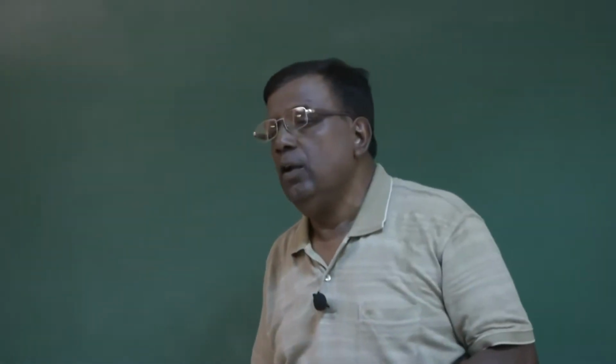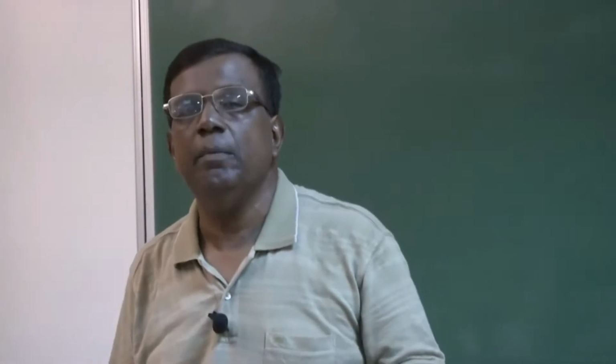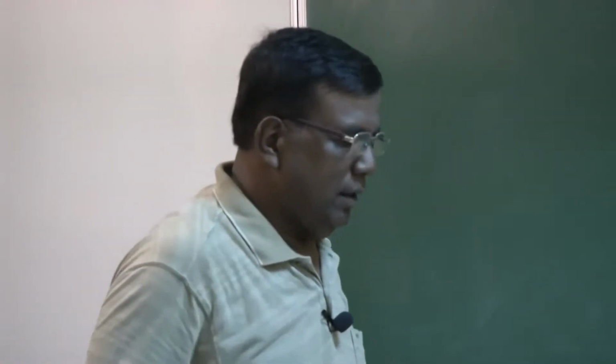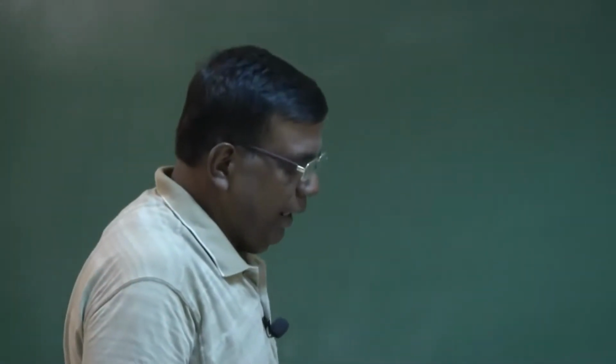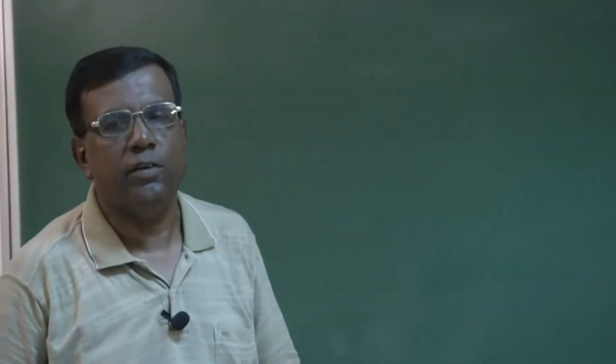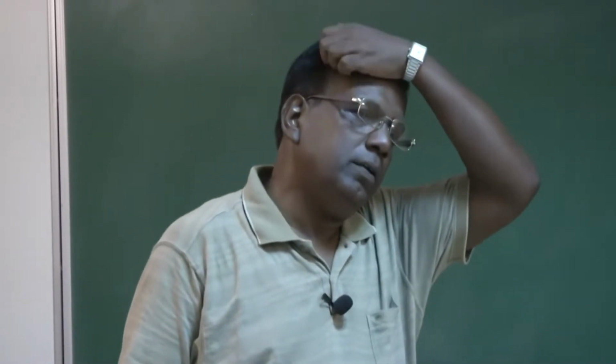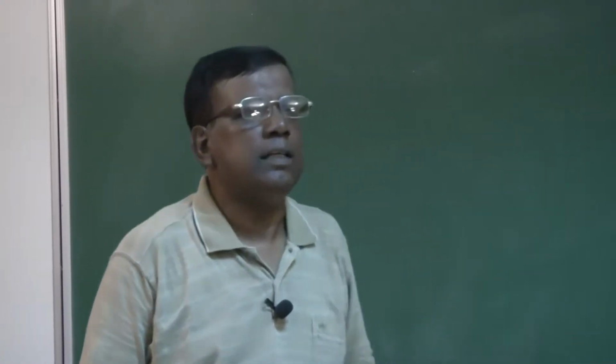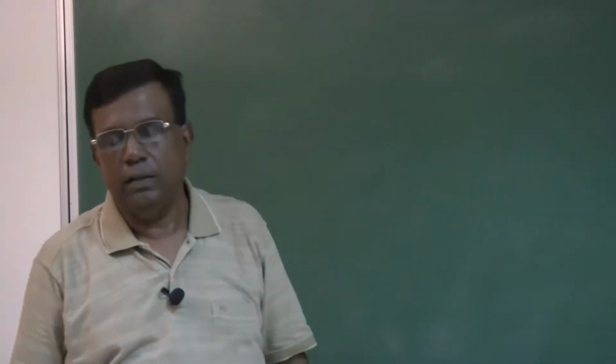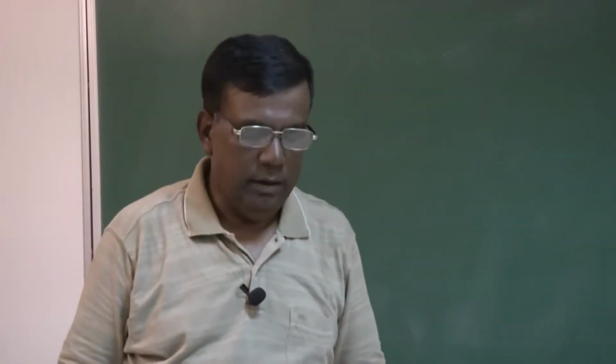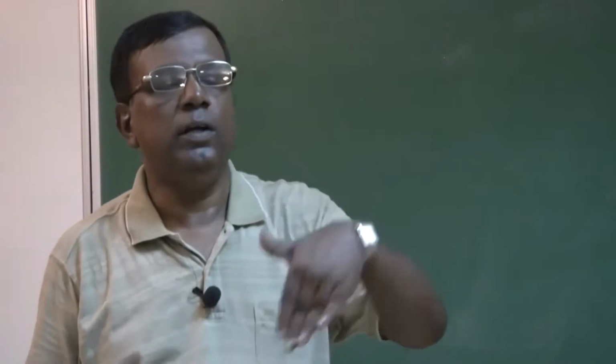Yes, dear friends, now we have gone one more step and we have seen for a mass spring damper system of second order in nature, how do I analyze what is the mathematical background or trick or technique required to find out the damping ratio and natural frequency. It is more important to make our understanding very clear that a second order system need not oscillate. It will oscillate or it will come to a return without oscillation.